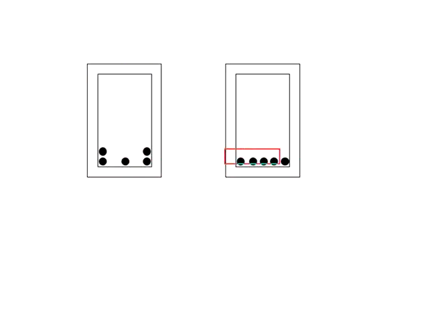You can have all 5 units of reinforcement in one layer, or you can arrange the reinforcement in a double layer with 3 bars below and 2 bars on top. Of course, the priority shall be given to one single layer, provided that the minimum spacing is fulfilled. If the reinforcement is too congested, then you will need to stack the reinforcement for a greater spacing between the bars.